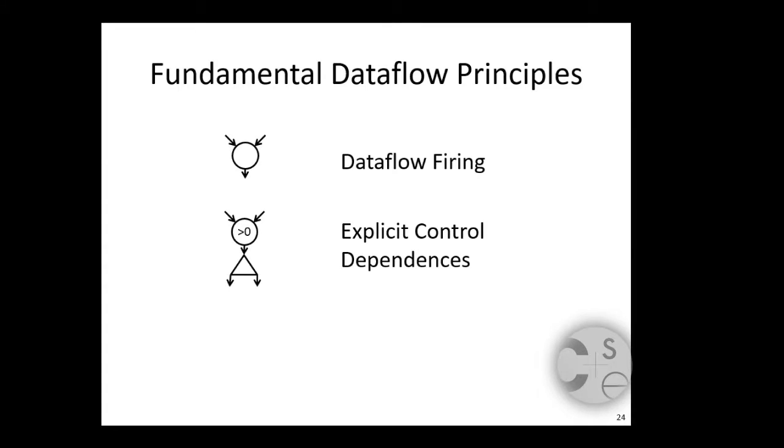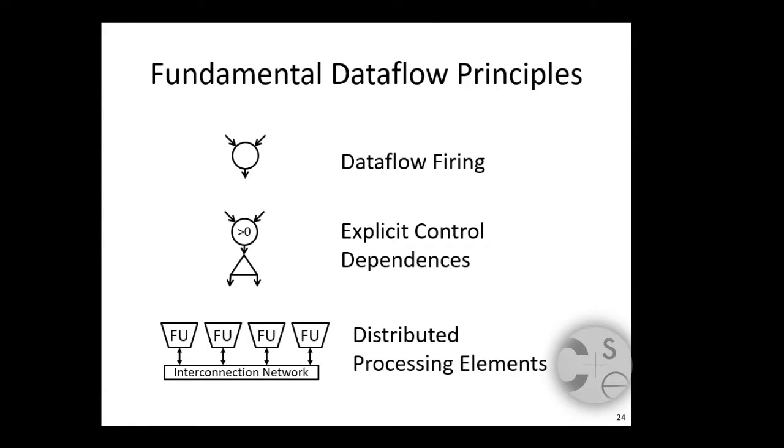So in this Dataflow architecture, I'll employ many fundamental Dataflow principles like the Dataflow firing rule to tolerate changing memory latencies. I'll employ explicit control dependencies that I won't do speculation on. And I'll use distributed processing elements to get high amounts of instruction level parallelism.